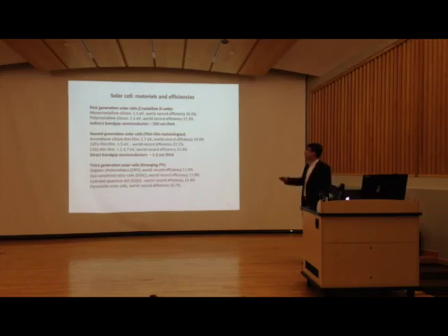And these materials, of course, are quite thick. If you look at a PV panel, it's pretty thick, but the solar cell itself is actually quite thin. It's about 200 micron in thickness. So for the second generation of solar cells, there are 3 types of materials. One is called amorphous silicon solar cells. The world record efficiency is about 14%, which is low compared with the others.